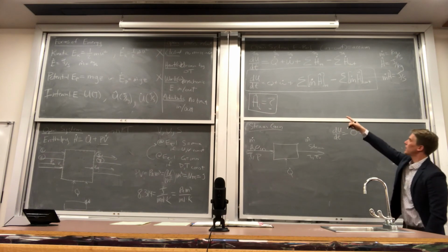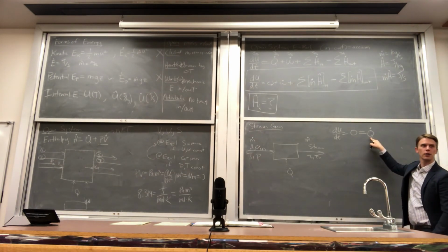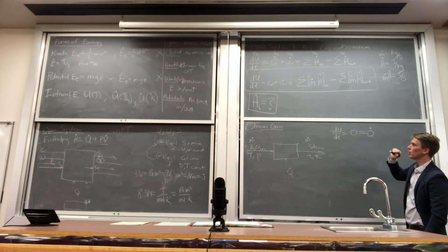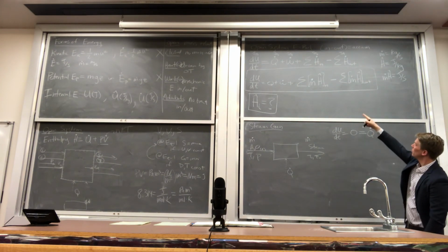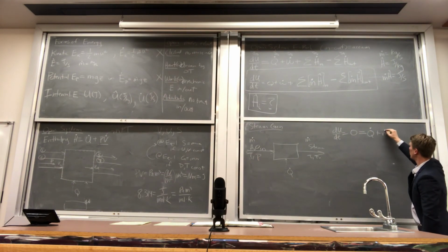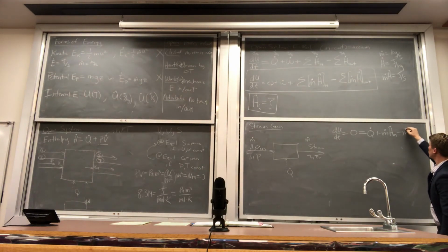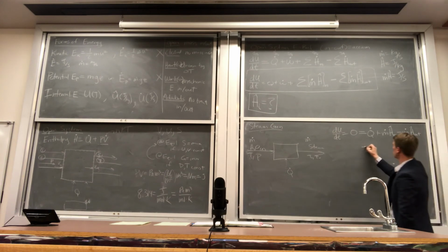Now let's go next. What's next? We have Q. Yeah, we still have a Q, and it's still positive, so I'll still draw it as a positive Q. Work, we don't have any work. Flowing into the system, we do have some energy flowing in. We have the mass flow rate of the water times the enthalpy flowing in minus the mass flow rate of water times the enthalpy coming out. Now what we can do is we'll just simplify this expression a little bit.